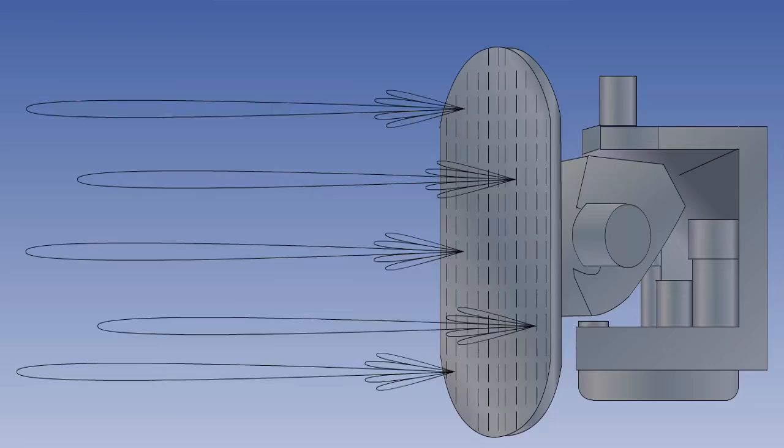A much smaller type of radar antenna is the flat plate or slotted planar array. We have seen with the ILS localizer antenna that if a series of antennae are spaced at half a wavelength and are fed in phase, the energy from the antennae is enhanced.